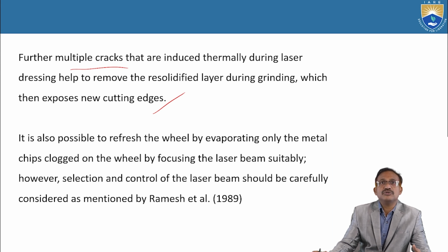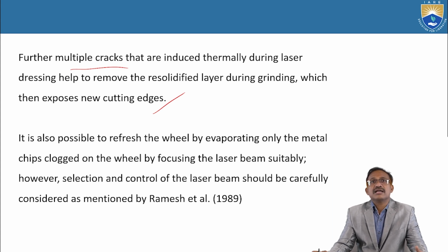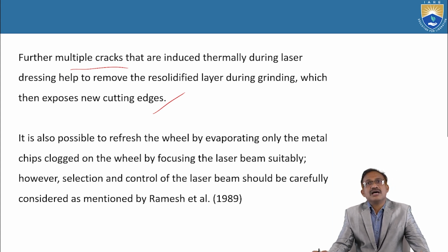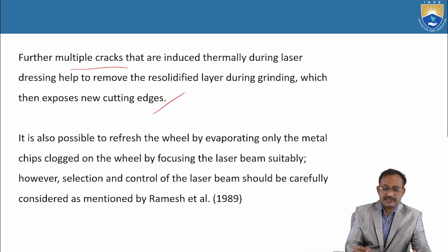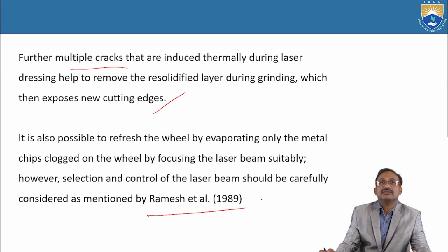It is also possible to refresh the wheel by evaporating only the metal chips clogged on the wheel by focusing the laser beam suitably. However, selection and control of the laser beam should be carefully considered, as mentioned by Ramesh et al. in 1989. It seems he is an Indian author who has worked on these laser beam machining parameters.